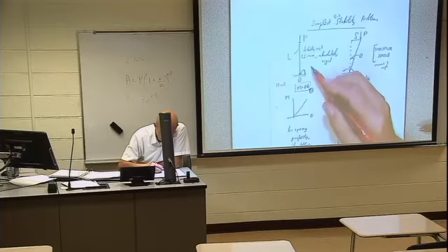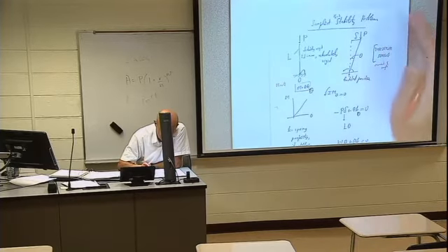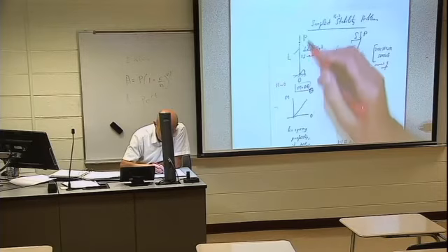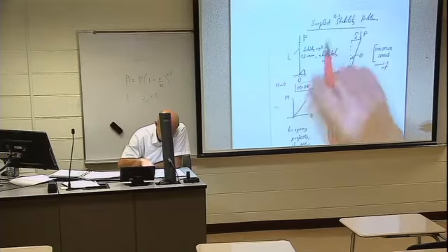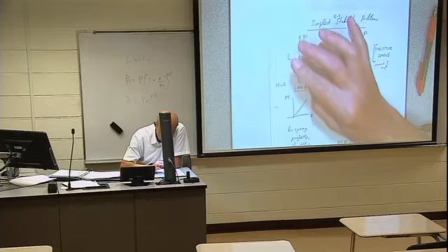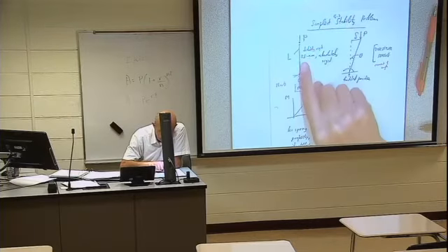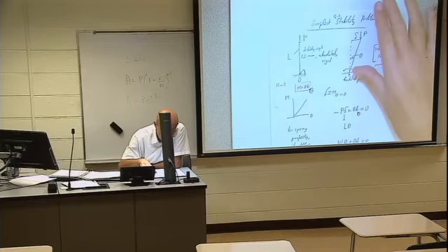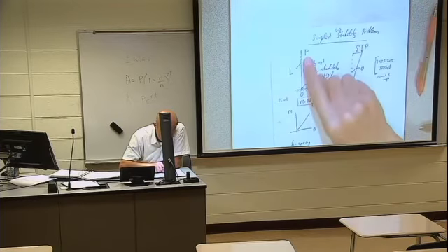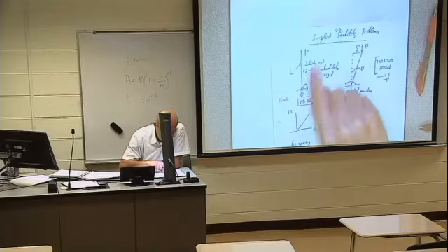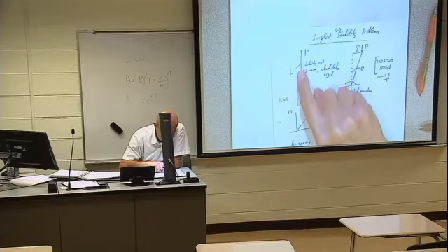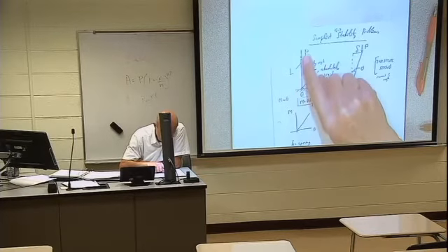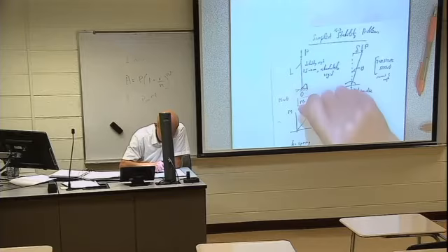Now, if you remember, our buckling experiment was like this. We put some force here, then we give a kick to the system. Then we take out this kick, like random wind loading, for example. Then this beam comes back to the original condition. Then we increase the load, and again we give a kick.